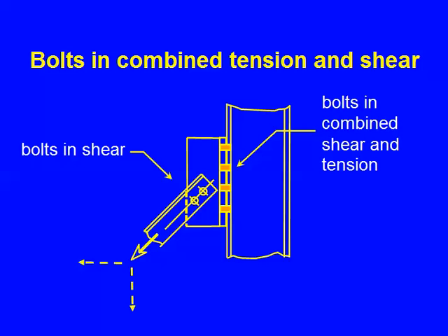And it's one of those situations where most failures are not unique to one feature. They're a combination of they didn't do this and they didn't do that, but one predominates. Certainly there was a lot of prying force in that connection, and that was a feature. Interesting that we don't want failures, but we should extract whatever information we can get from them and learn.